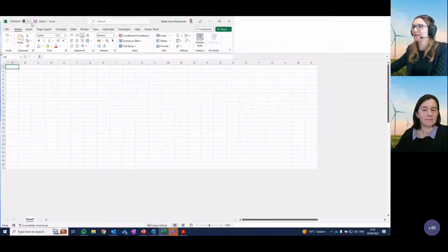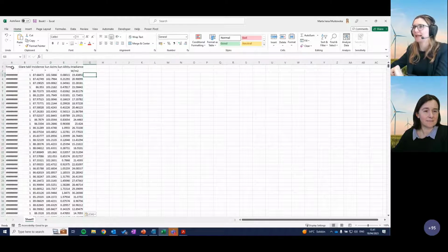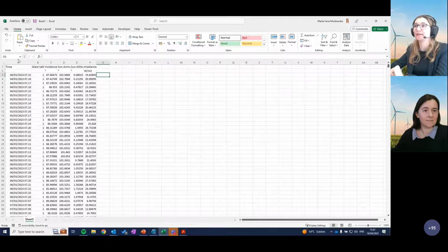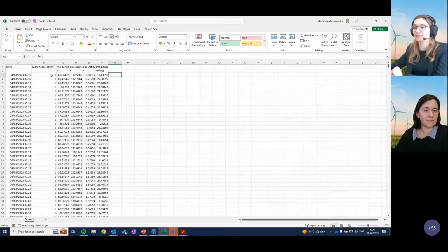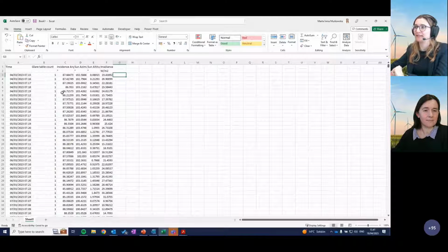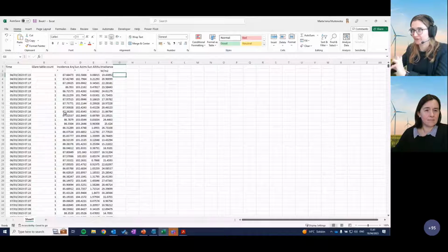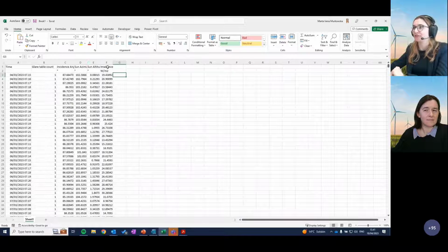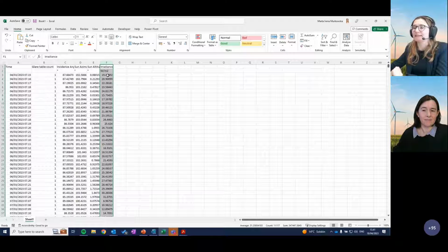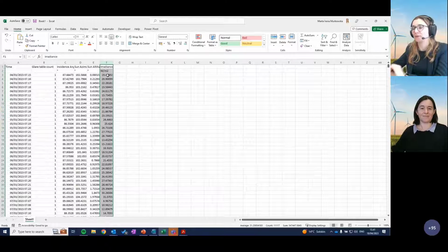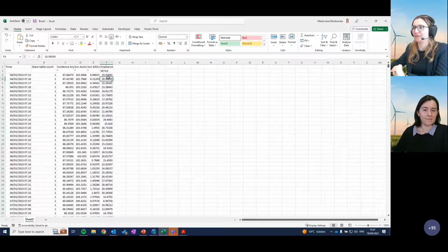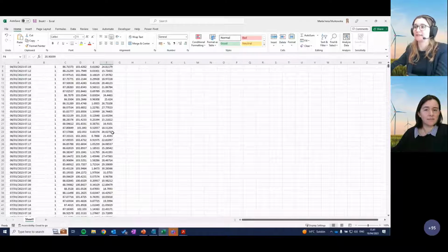Then we can put it in Excel and paste it. In our result to file, we offer all time steps in which we could see glare occurring, together with glare table count, saying from how many different tables the glare came, and the incidence angle on our reflective surface, the position of the sun, and finally the irradiance. So the reflected irradiance from the PV panel in each of the time steps is calculated using the reflectivity model, as well as taking into account the exact incidence angle on the reflective surface. So everything is considered here, and per time step you can see how intense the reflection was.